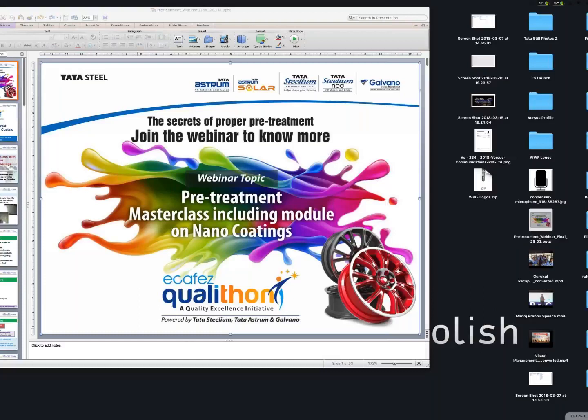Mr. Sridhara KM asks, in degreasing, what is the maximum oil removal percentage, and how frequently do we have to replace the water? Now, I feel you are talking about replacing the rinse water. The replacement of this rinse water is dependent on your pH levels.